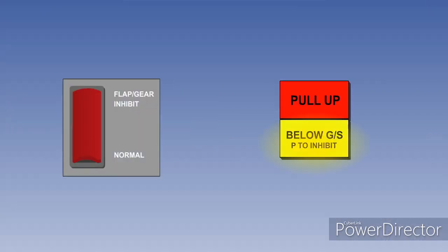The two times when the GPWS EGPWS would need to be inhibited occur during the approach phase. These are either if the flap gear positions are known to be non-standard, or if the crew are flying an approach without regard to the glide slope.